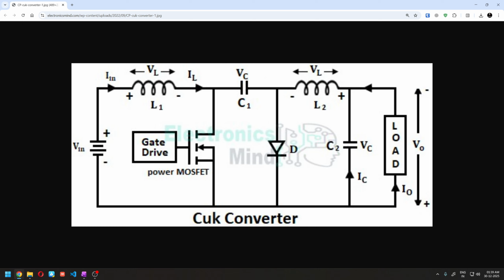So the Cuk converter is sort of like a mishmash between both of them, the input and output, and in between there's a coupling capacitor, as they call it. That is what is going to transfer the energy from the input to the output. And that is what makes this converter good, in the sense that it has continuous current drawn on the output. So there are fewer pulses, it's not pulsed, it's continuous, so the EMI goes down a lot. So yeah, it's a continuous current converter.